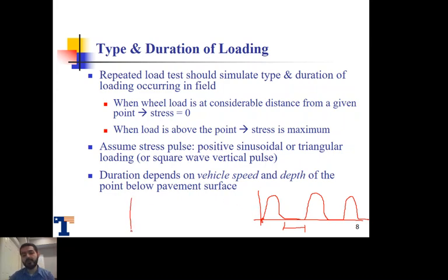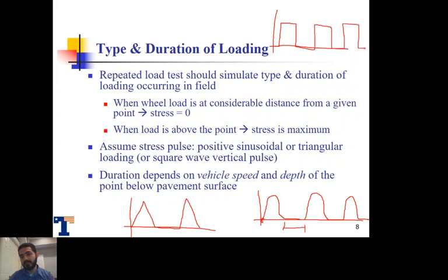A triangular loading is similar, but the way it's done, again, it's very sharp. And then we have here a rest time, and then we start again. So again, those are the two schematics that sometimes we use, but we tend to use the sinusoidal loading more than triangular loading. Or sometimes we do a square wave vertical pulse, not something like this. So it starts from zero, something like that. So there are again different types. Again, forgive my drawing, it's not the best. I'm using the mouse here, but you got the point.